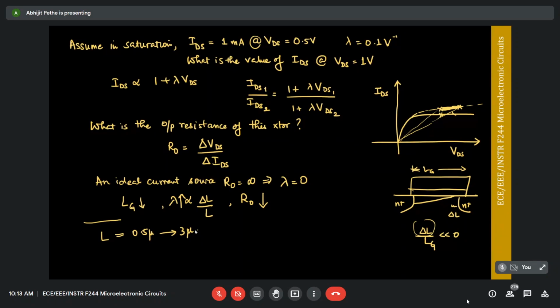So you can't fit more of them on the same chip. Area, right? So basically, analog design therefore consumes a lot of area. Now, the good part about analog design is that generally in SoC design, analog by itself is a small part of the design. Most of the design area is consumed by memory. So you don't have to worry about spending a lot of area on design.